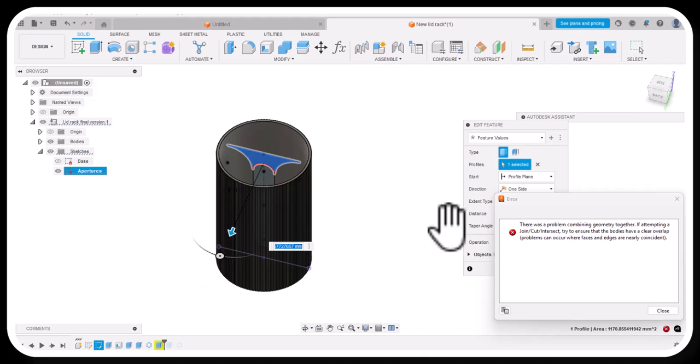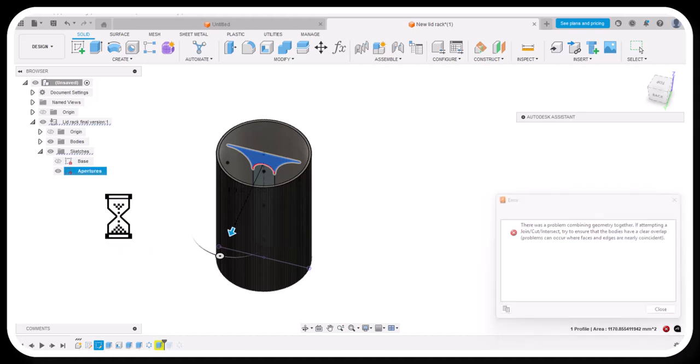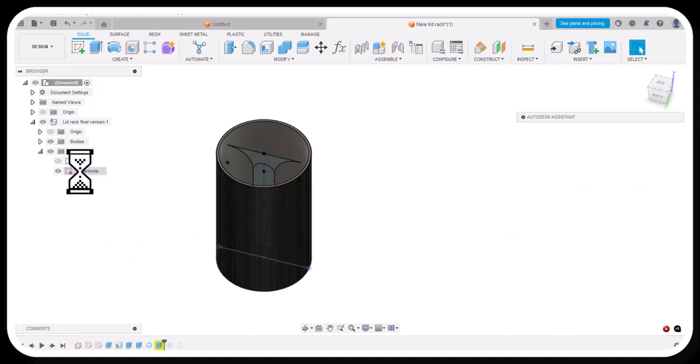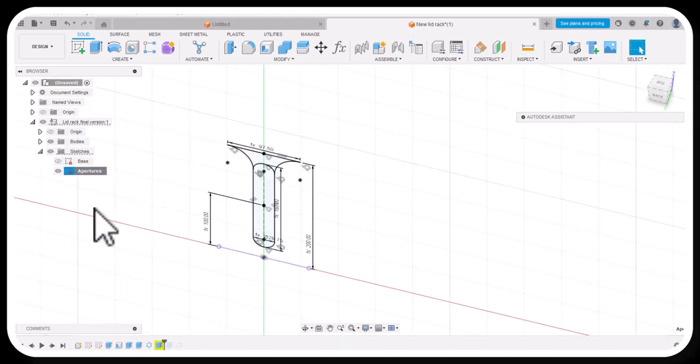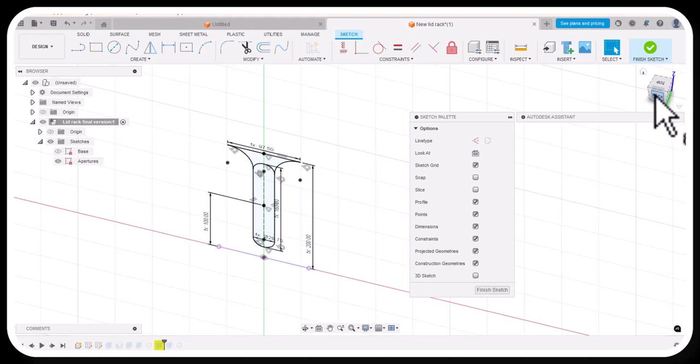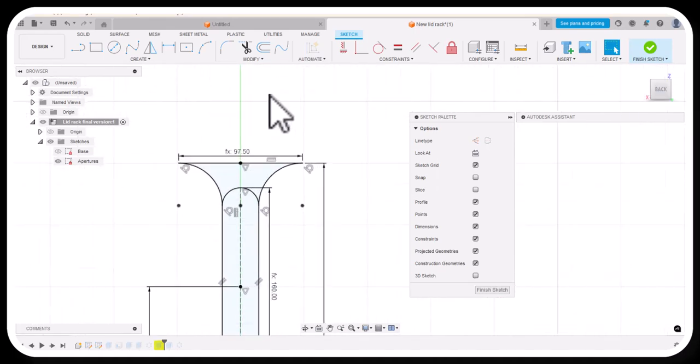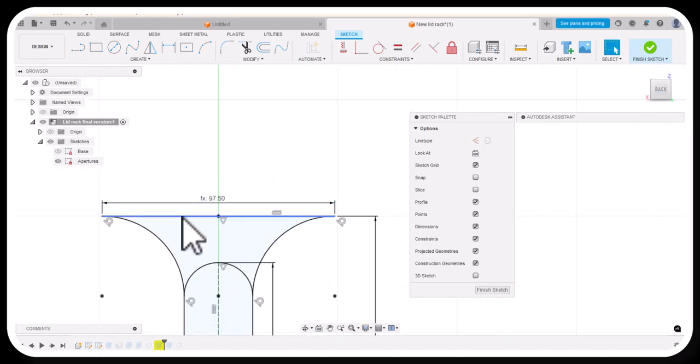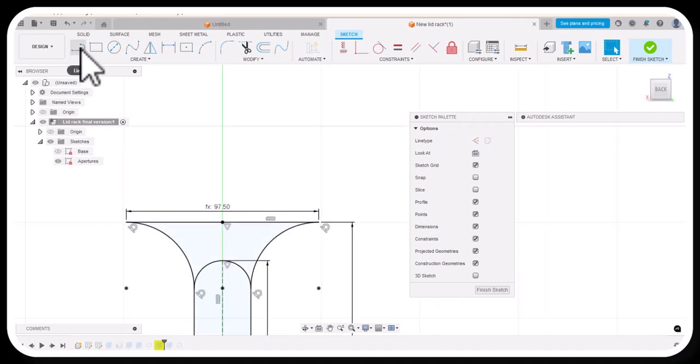So I'm going to edit sketch number 2, and let's get out of the command, we were partway in it. Let's edit sketch number 2, and I'm going to look at it where we're looking directly at it. And so this top edge is nearly coincident, or it's confused there where that top edge is. So I'm going to help it out.